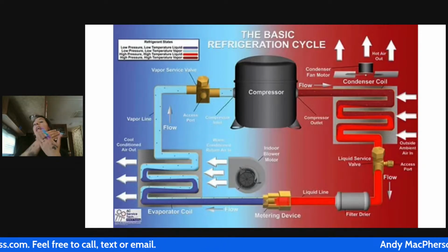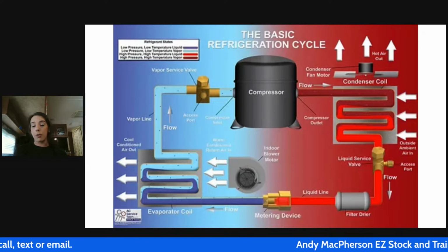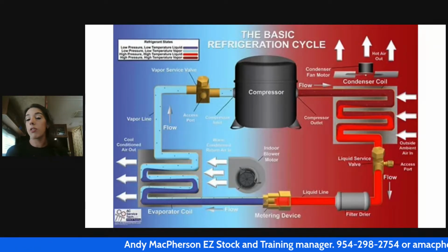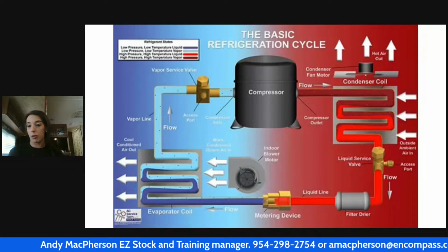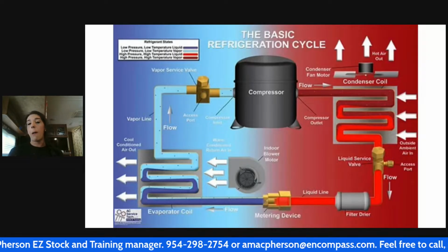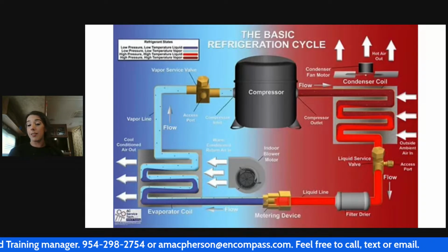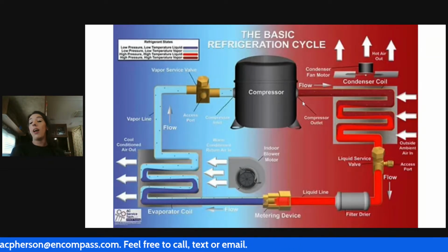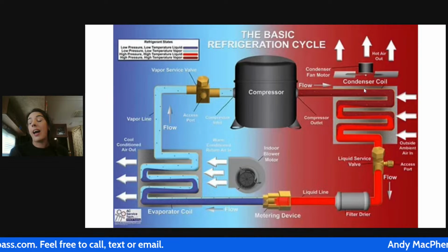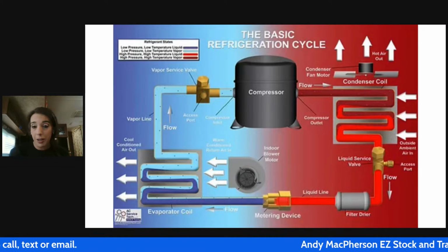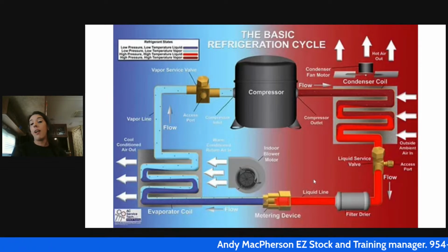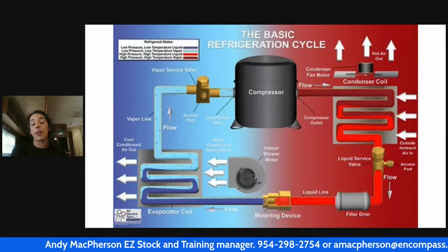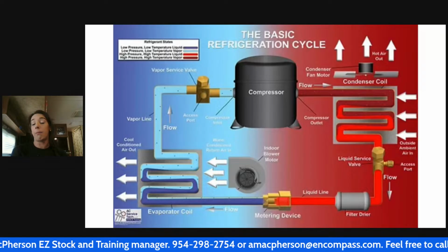Now, a lot of units, especially inverters, a lot of the new units we're seeing, a lot of refrigeration units as well, have accumulators or receivers. So those will help a little bit if we have an overcharge situation. They'll help to keep that liquid out of the compressor. But in the majority of units, they're older. They don't have those. They're not for refrigeration, they're for AC. And so instead, that excess liquid that we just jacked into that system that wasn't low to begin with now ends up back in the compressor. That compressor tries to pump the liquid. It can't. It eventually breaks a scroll, or it acidifies, or it ends up having complete burnout.